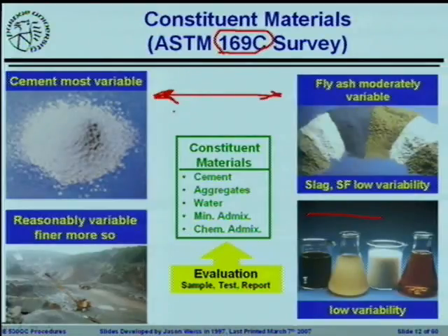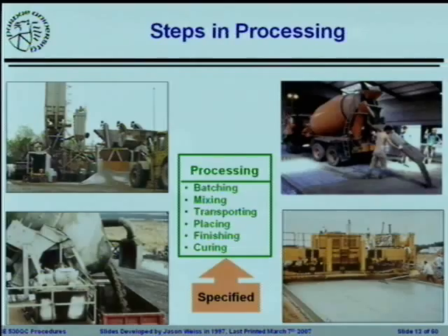I think what does change is cement coming from one place to another, and everyone thinking that all type 1 cements are created equally. Depending upon where you're getting your materials from, you can have either extremely repeatable supplementary materials or incredibly variable materials. The main thing that we're looking out for here, fly ash carbon content, will tend to be one of the things that varies the most.